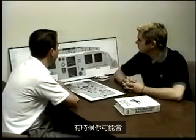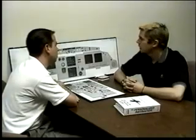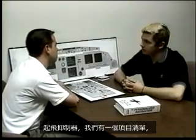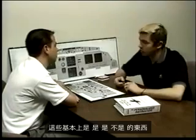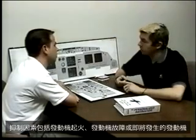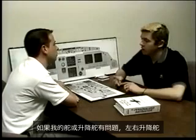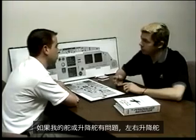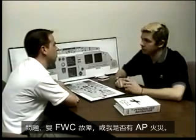Are there some times that you might have an inhibit of master warnings or even certain ECAMs? Yes, there's the takeoff inhibit and the landing inhibit. The takeoff inhibit, we've got a list of items that are included on the takeoff inhibit. Those are basically things that are not inhibited, like engine fire, engine failure, or imminent engine failure with a loss of oil pressure. If I have a rudder or an elevator problem, a left and right elevator problem, a dual FWC fault, or if I have an AP fire.